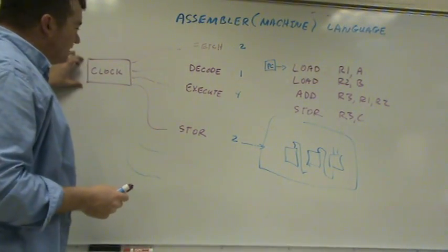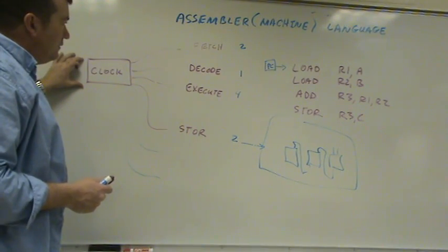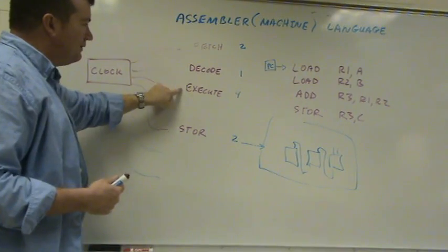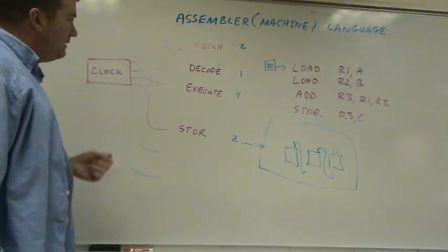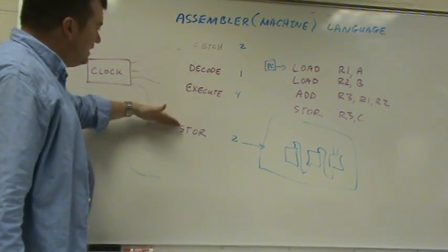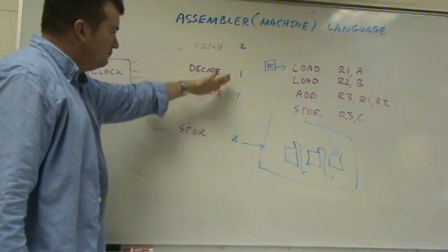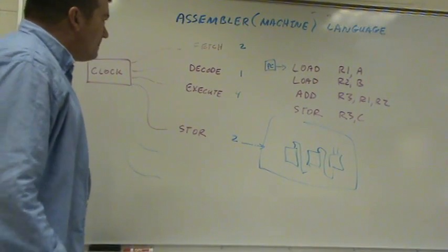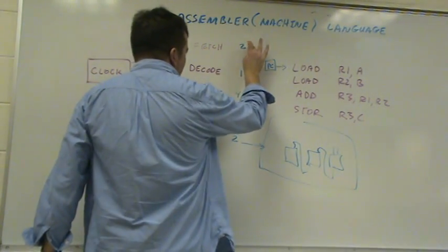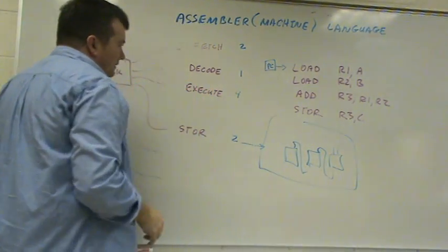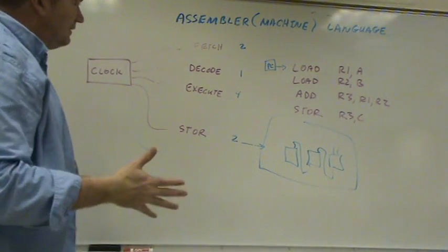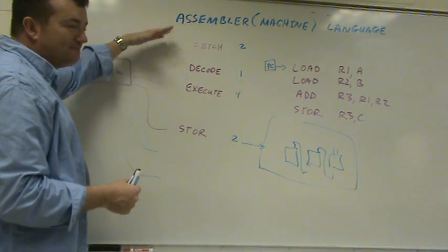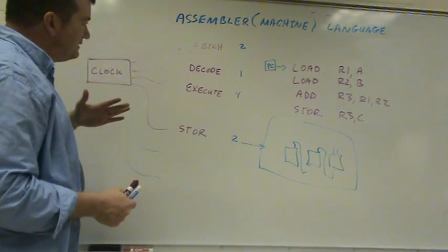We would have to set the clock speed to allow 4 units of time for all of these steps, because one of them needs 4 units of time. So to go through a whole instruction would actually take 16 milliseconds, or whatever these numbers are, when really all we needed was 2 plus 1 plus 4 plus 2, 9. But because we broke these into 4 separate steps, it ends up taking 16.